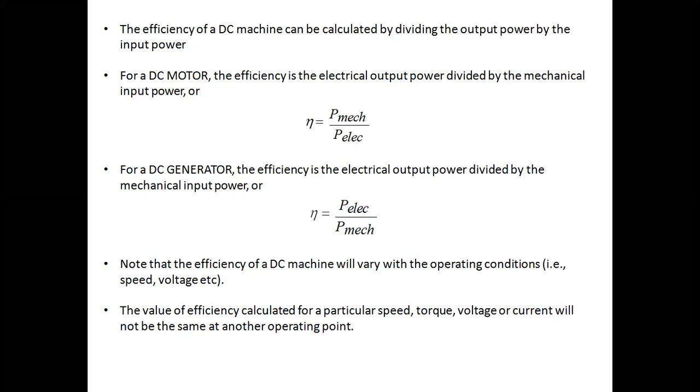Like, you will require the equation for a DC shunt motor when we give the supply. At that time, you will get that voltage will be equal to EB plus IA RA, because when you connect the DC machine, there will be some amount of resistance RA, and some current will flow through that.